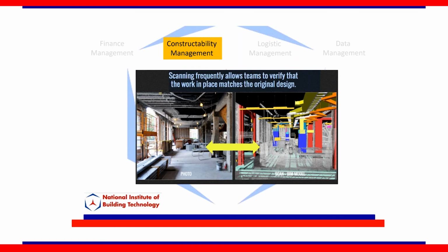And it's going to alert you in 2 ways. Say, hey, the column moved, what do we do? Is that okay, or do we need to rectify the issues before it becomes an issue? Because right now no one even knows it's an issue. The second would be, let's say there's a duct or a plumbing system or anything, a bus duct, electrical systems in place where they're not supposed to be, if someone accidentally installed it, before the next trade goes in and creates a problem and it becomes a crisis on the field, this point cloud will tell you, by the way, this person is not where he's supposed to be. So we need to fix it before the sprinkler person comes in and starts to put a pipe where he's supposed to, and they won't meet and there will be a clash.